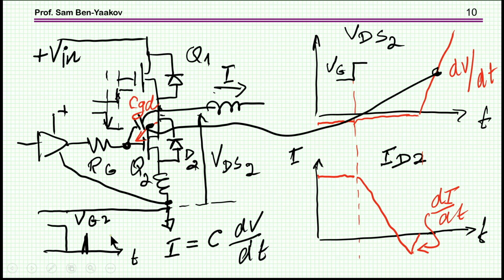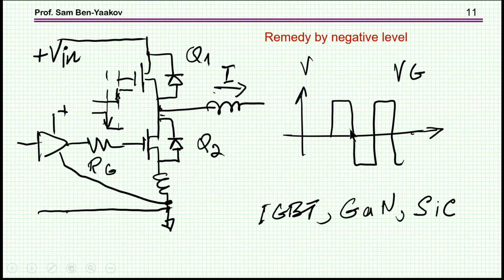So these are some of the reasons that you might wish to go to a negative voltage bipolar drive of the MOSFET. For IGBTs, this could be very important because IGBTs are large elements, inductances are relatively large, capacitance is large, and therefore it is customary for the IGBTs to have a bipolar drive. It is also correct for devices that have a narrow range permissible for the VGS. For example, a certain GaN transistor has only a 0 to 6 volt range for driving. Above that, it could damage the device. So it can go negative too.